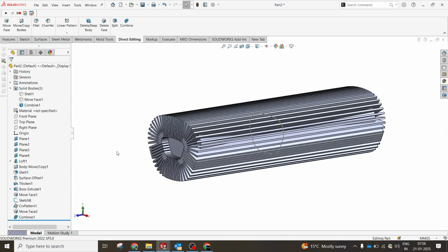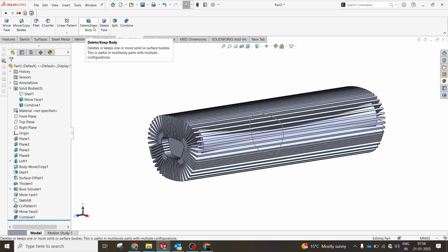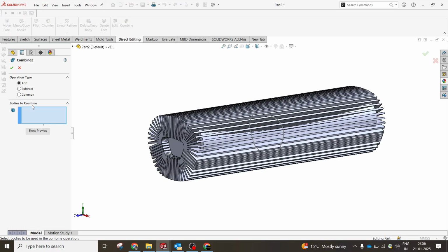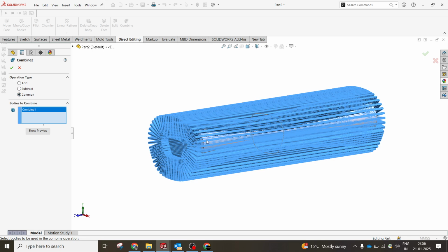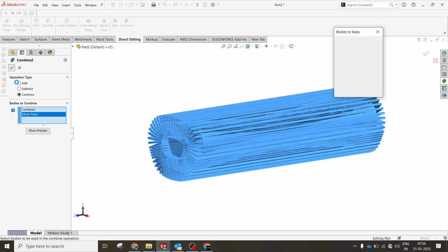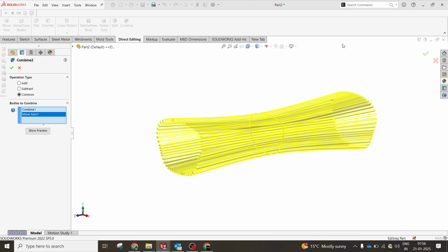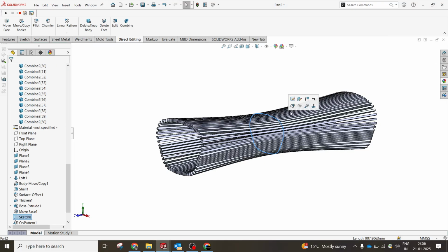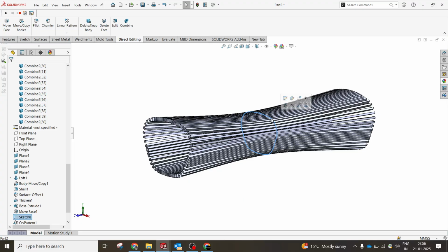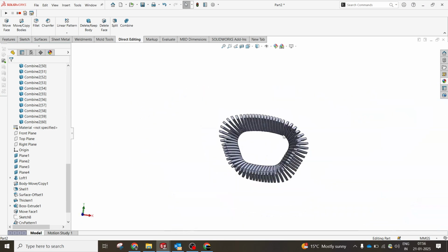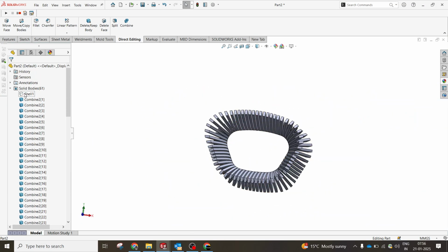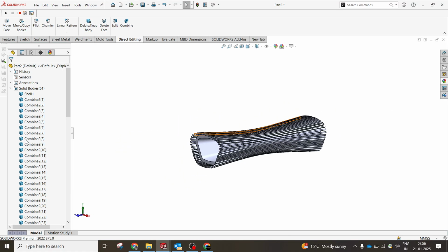So in order to crack that, these two which we are going to subtract from each other, yes, combine, which is common here in both of these two. So you want to select common, so that only the particular parts will be there. We want all the parts, all the bodies. I'm going to select that now. This is ready, and I'm also going to enable a shell option, yes.